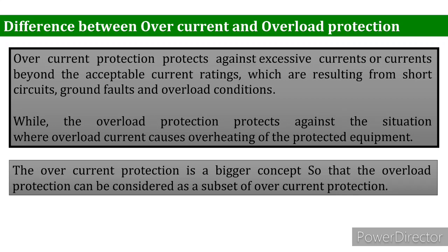For example, with motors, if the winding of the motor gets heated, it falls in overload protection, because there is a clear chance that it may burn out. And overload protection is a subset of overcurrent protection because, as a basic concept, we know that if current flows through any wire, it produces heat.